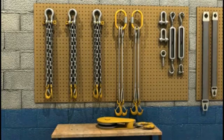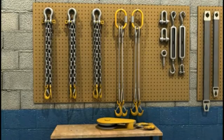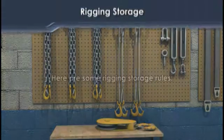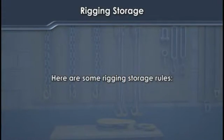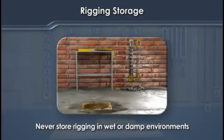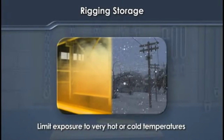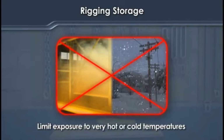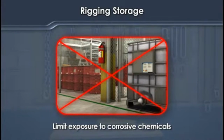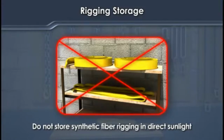It is important to store rigging in its assigned storage location. Leaving the rigging in improper locations can lead to rusting, corrosion, and other damage. Here are some rigging storage rules. Never store rigging on the floor. Never store rigging in wet or damp environments. Limit exposure to very hot or very cold temperatures. Limit exposure to corrosive chemicals. And do not store synthetic fiber rigging in direct sunlight.